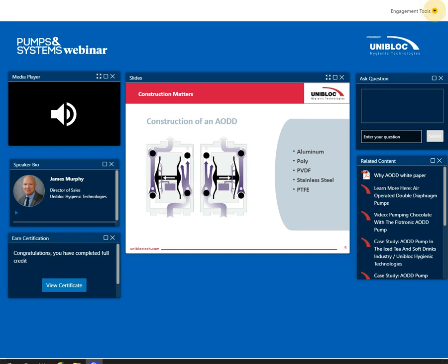So this gives you a little bit more of an up close look of the actual pumping mechanism here. So you can see in this configuration, you've got the check balls, which are obviously those 4 black balls. And then you've got the 2 diaphragms, one on the left and one on the right. And as you can see, the media is represented by the purple color.